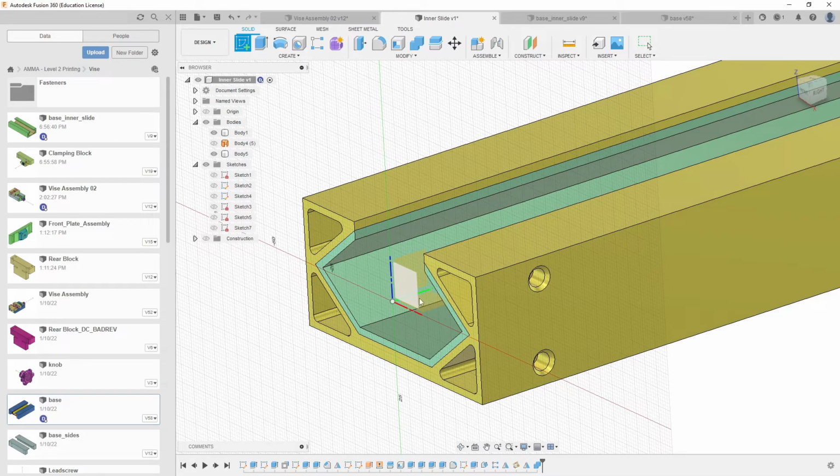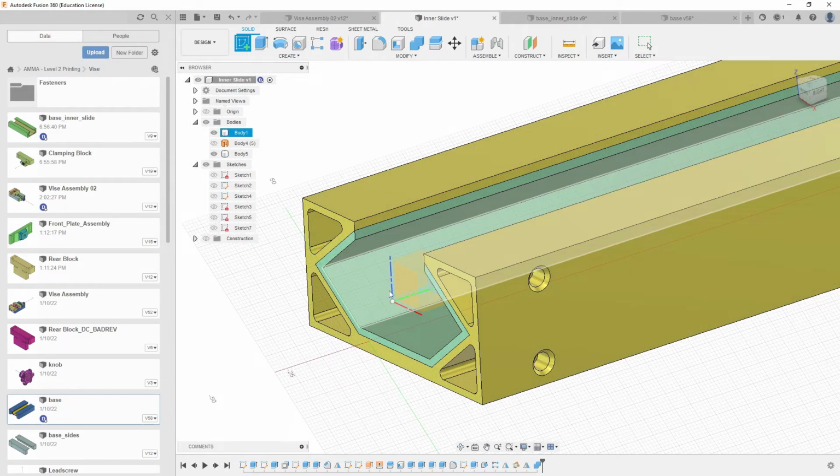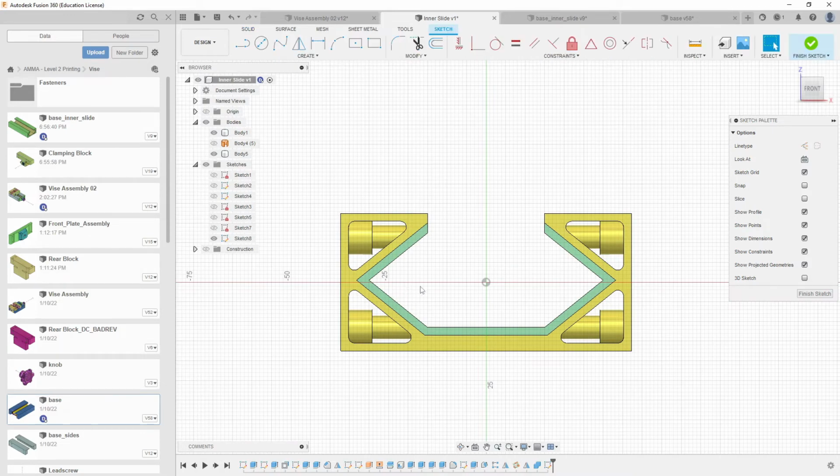I can tell you, I was careful about this when we began. The original square that is the yellow that ended up getting subdivided and all that was all based upon this sketch right here. This is still true. This is flat with this. If you ever needed to, measure it. Hit inspect from here to that flat face, see that it's 0. So I'm going to pick this, and I'm going to make this the front.